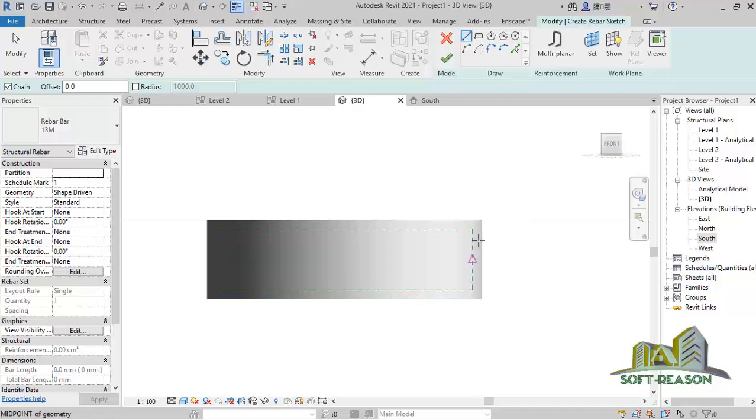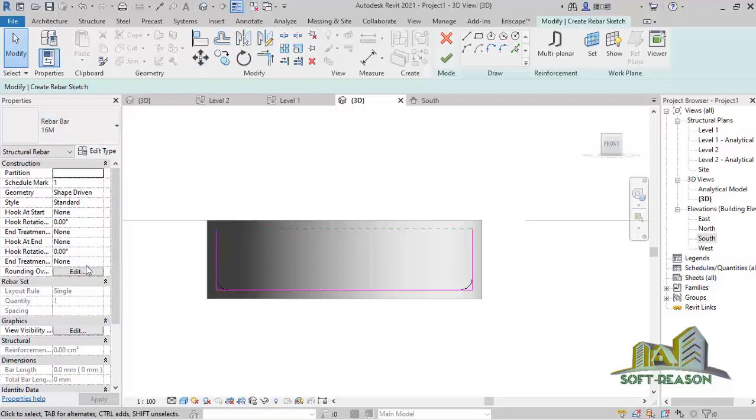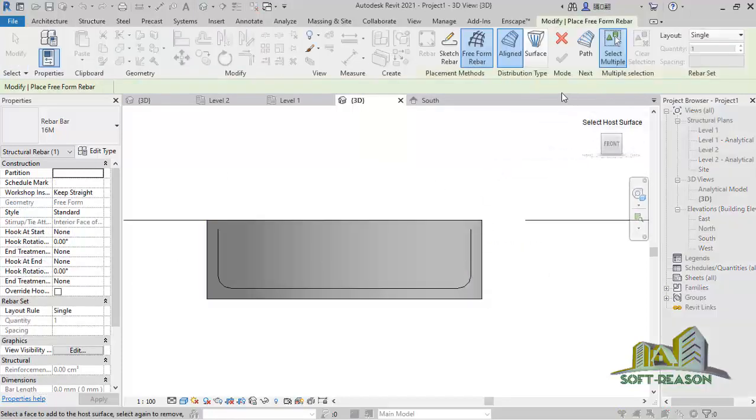to sketch my footing. So I want to start the footing from this point, as into for me to sketch my reinforcement. So I want to start from this point, pick that, go straight away to this point, pick, and then also pick that point. After having that done, I will escape that command. Alright, then click on modify. Come to these provisions. This rebar diameter I want to be considering 16 mm. Alright, after that is done successfully, click on finish. And then I will finally finish that.